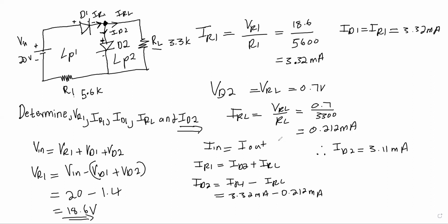That's it. To answer questions based on diodes and application circuits, you just need to know how to draw the direction of a current and their relationship, and keep in mind that a diode has 0.7 volts present.